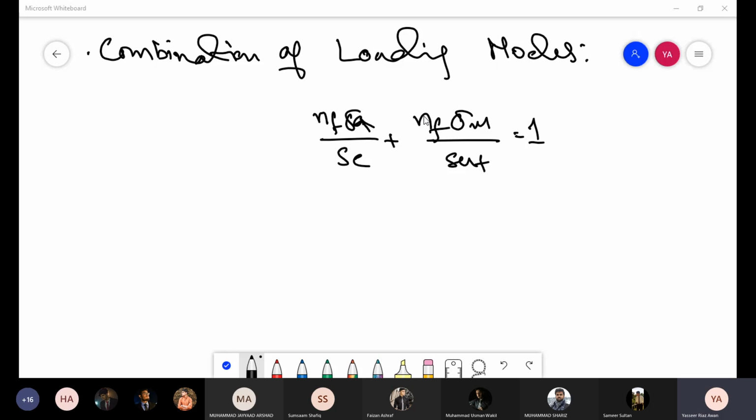Okay, sorry for the delay. So we were discussing the combination of loads. That means that instead of pure axial, pure torsion or pure bending, we have a combination of these. And we also have the fluctuating stress case. So you want to use the modified Goodman equation, but now there is no single alternating stress.